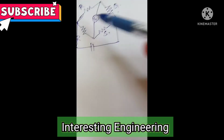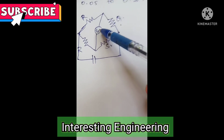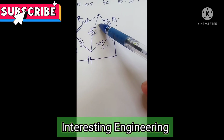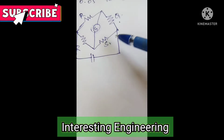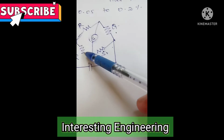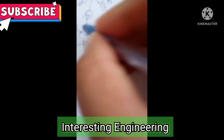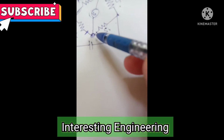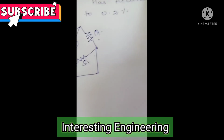This unknown resistance is measured in terms of the standard resistance under the bridge balance condition, which is nothing but the condition where the current through the galvanometer is brought to 0. Under such a condition, we make the measurement by adjusting this variable resistor to measure the unknown value of resistance. But in this case, there is a problem of lead resistances and contact resistance. This causes error in our measurement. That error is eliminated using the Kelvin double bridge method.